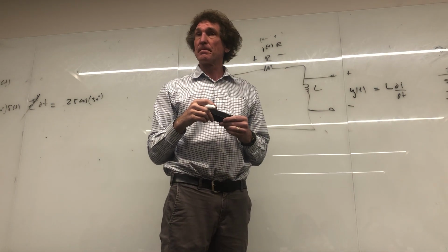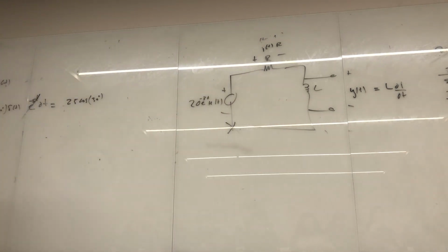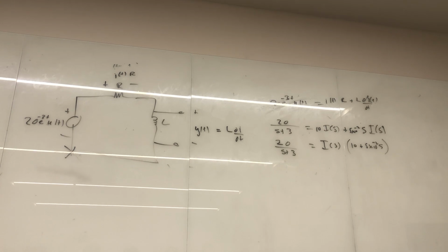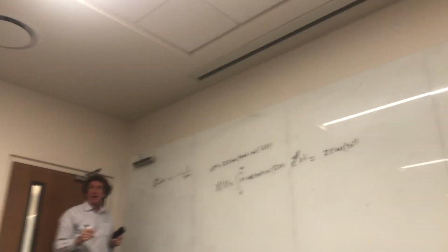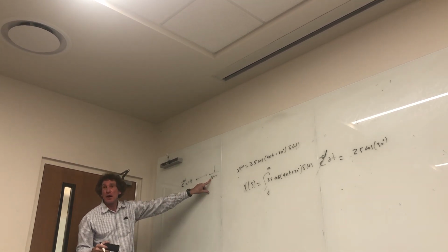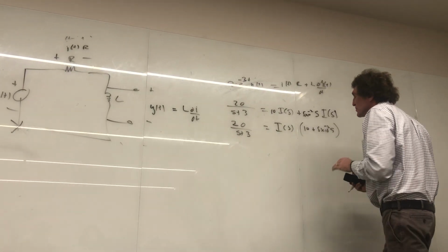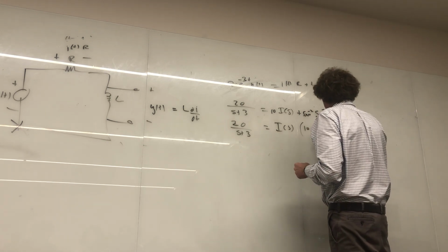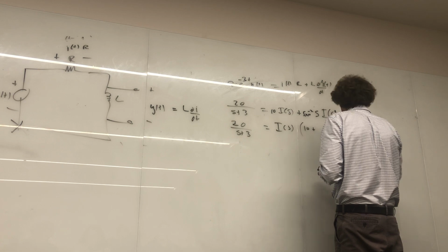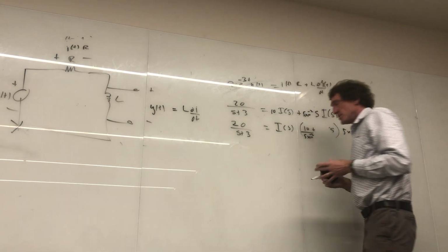You with me on this? Now here's the first thing I'm going to call your attention to. Anytime you have Laplace transforms, for exponentials you have e to the minus at u of t, which pairs as 1 over s plus a. Agreed? What that means is the coefficient of s has to be 1. If you look there, our coefficient is 5 times 10 to the minus 2. So I'm going to take 5 times 10 to the minus 2 out in front of this, and that means I have to divide this by 5 times 10 to the minus 2. Do you all agree with me there?